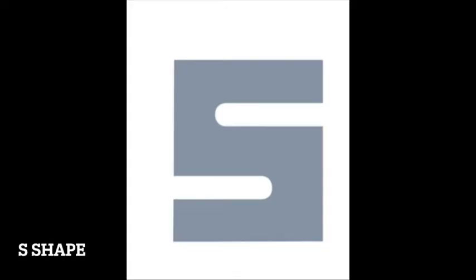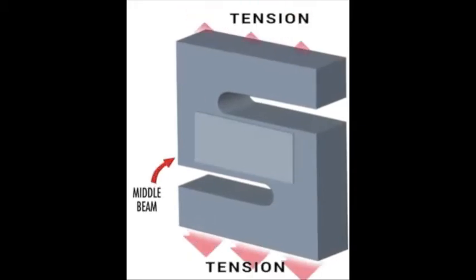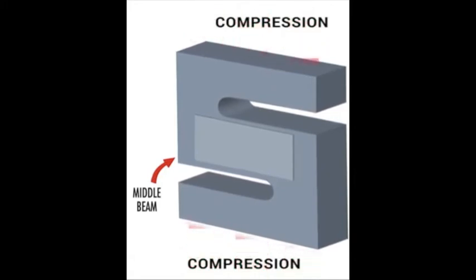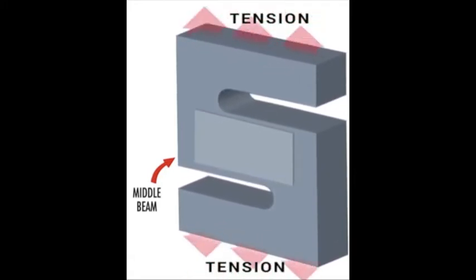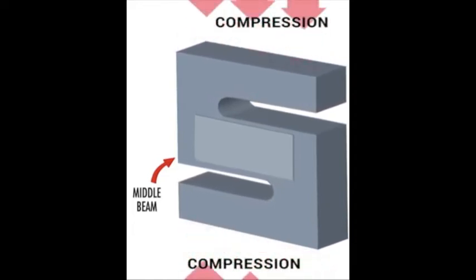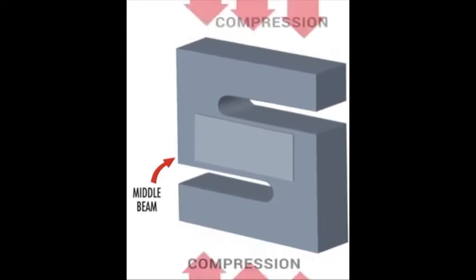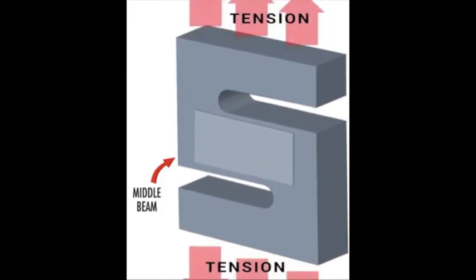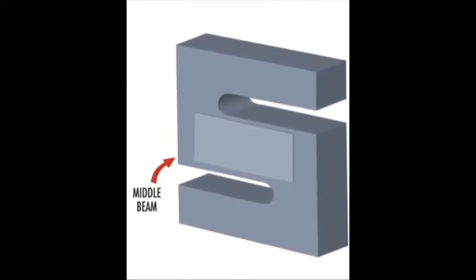S shape. A hot rolled structural steel section having an I shape with sloped inner flange surfaces, designated by the prefix S followed by the size and weight of the member, also called American Standard Beam. So S-shape is distinguished by its cross-section being shaped like the letter I. S-shapes are used less frequently than W-shapes, since S-shapes possess less strength and are less adaptable than W-shapes.